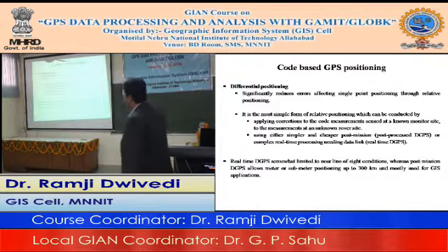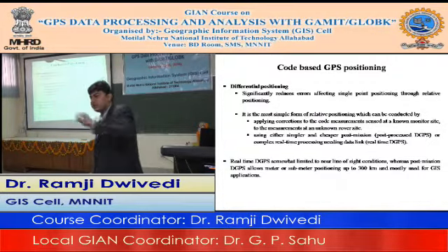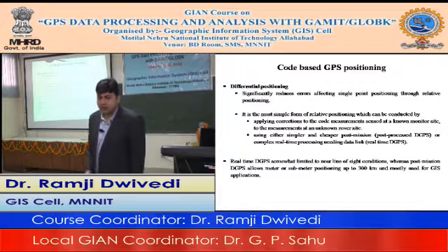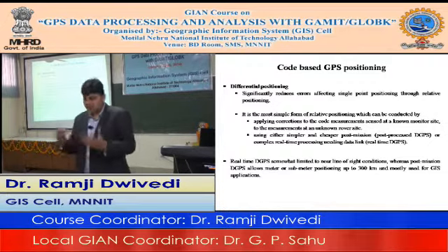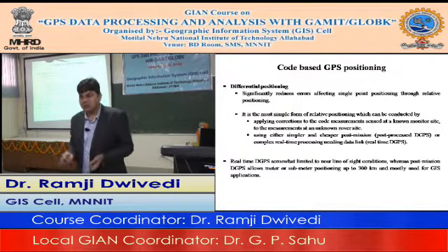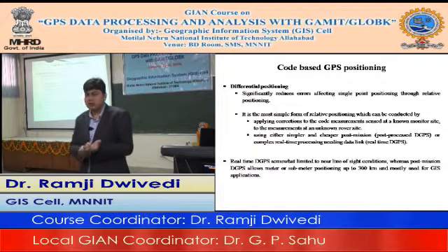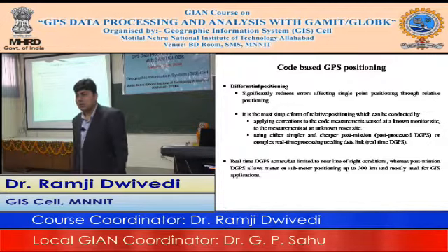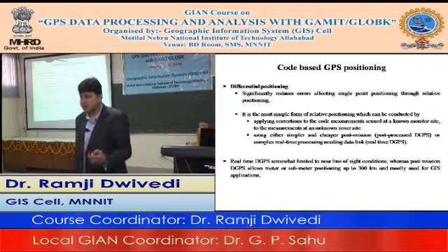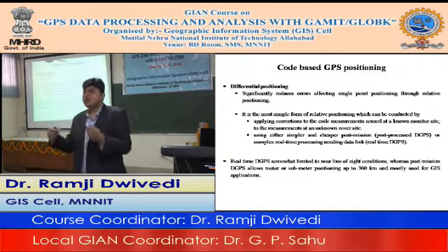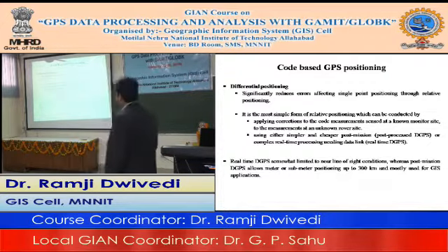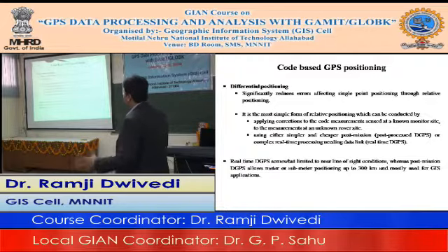You can also have a real-time processing data link, which can send the corrections to the rover, whether it's a radio modem link, or now network providers are there. You can also use a SIM in your devices and access the correction. But there are a lot of settings which you need to take care of. So real-time DGPS is somewhat limited to near line of sight.